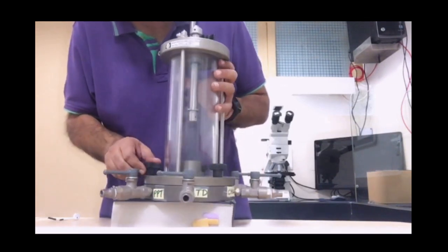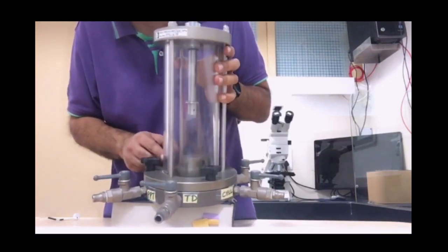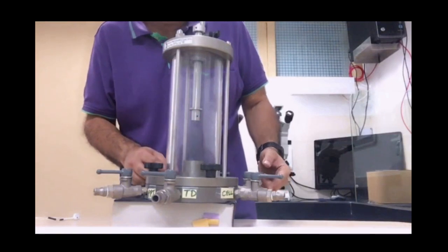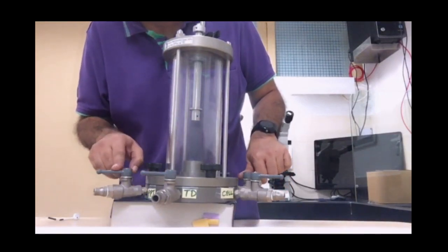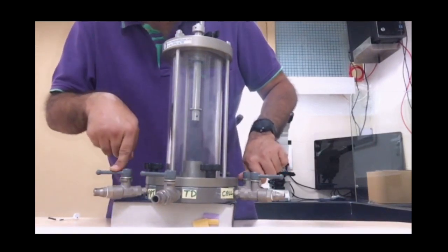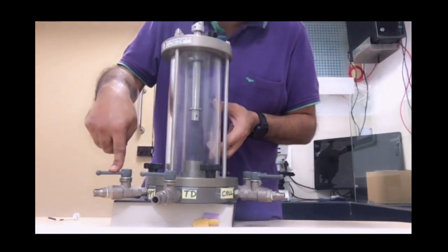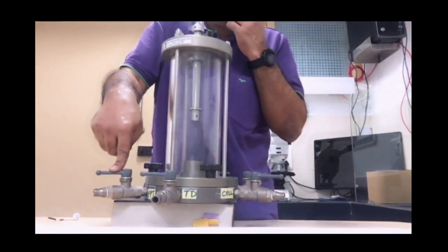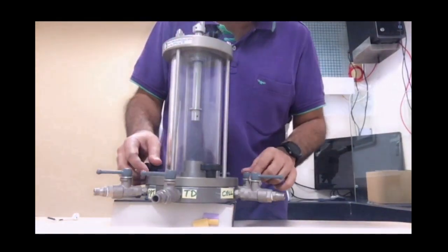Now there is one term which we used earlier, the short circuit. Remember we said both the holes are at the bottom. So if I apply 190, it's quite likely that the pore pressure transducer will read 190 immediately. So it may give you a false feeling that the pore pressure within the sample has stabilized and there is no more change occurring.